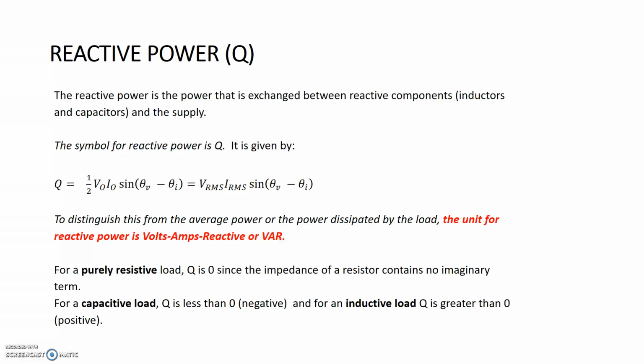If the reactive power is negative, that's a capacitive load. If the reactive power is positive, that's an inductive load, and we can figure that out by looking at this sign of the voltage. Okay, so that's reactive power.